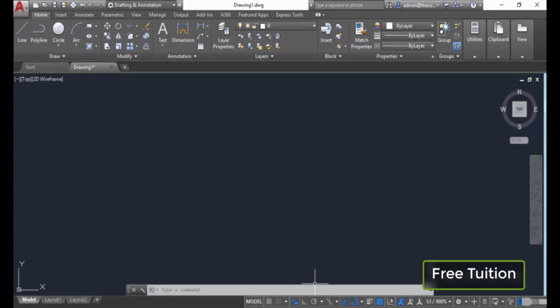If it is checked it will show like this blue icon. Just make sure it is unchecked. Also we have the ortho as well as the polar tracking. So make sure this polar tracking is on, not this ortho.